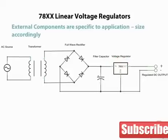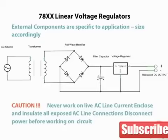External component selection is specific to the application. Always select components to meet the voltage and current requirements expected in the circuit. And never, never, never work on live AC line current. And close and insulate all exposed AC connections and disconnect power when working on an AC line circuit.